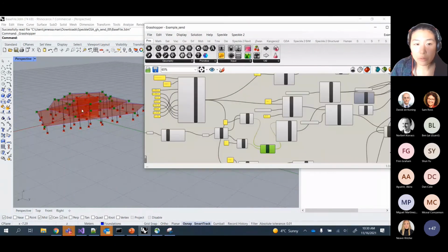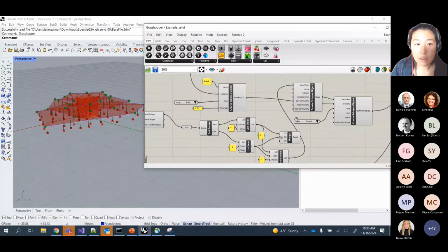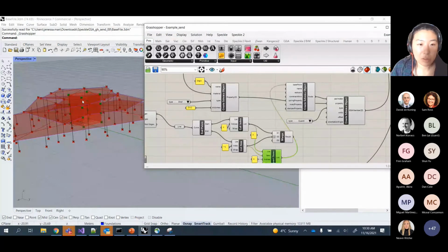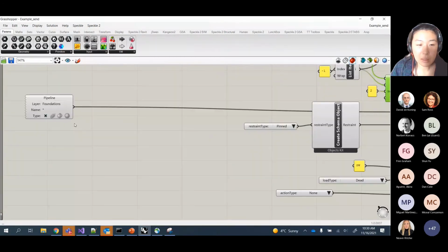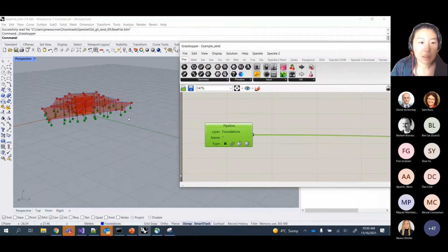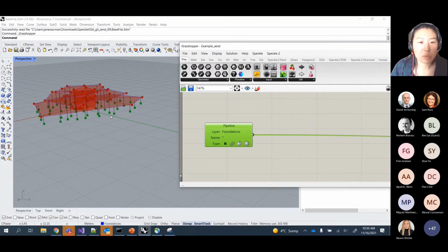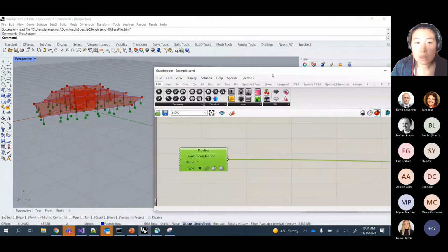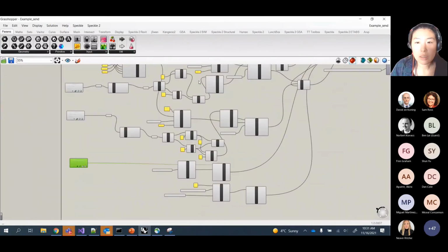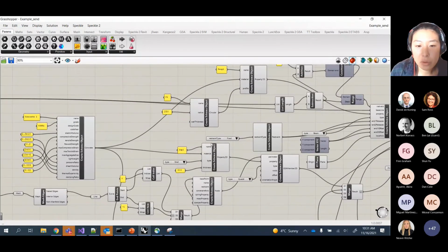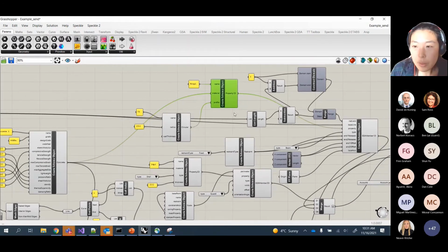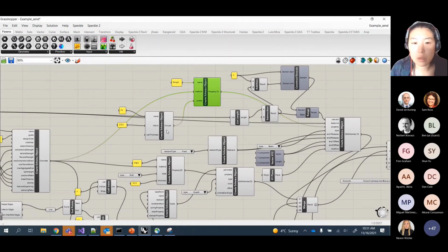And so we can do that for the floor plate, but we can also, of course, do that for the core as well, where it intersects with the floor plate. And to make this a little bit bigger again, in this case, we can also apply some restraints. So we'll say that we've got some restraints to represent the foundation at the bottom here. And these are based on the nodes that we've already modeled and added in our Rhino model, and a similar type of thing. So we'll create a property to assign to our column elements.